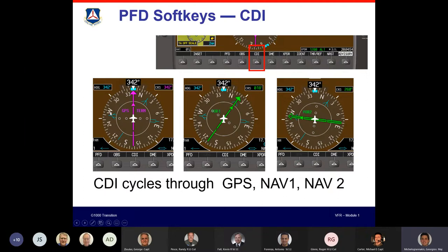These are called the RMI needles. And they are pointing to the nav1 is the single line, and nav2 is the double line. And they just point directly to their stations. So you don't tune the OBS setting or the CRS as it's called. They just point you directly towards them. So it's nice to use them to cross-check, like if you're going to use a cross radial to define a waypoint, they're very useful, or as a backup.